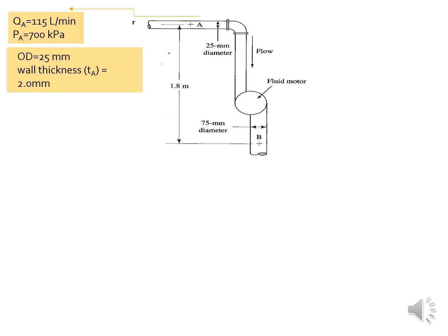It also provides the dimension of the pipe at A, at this point. This is the pipeline here. The outside diameter is 25 millimeter, and because it's given the outside diameter, it also provides us with the wall thickness. Be careful with this information, because the flow area that we are looking for is actually for the inside layer here.